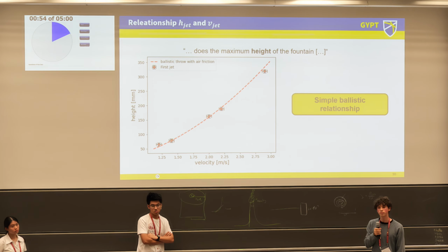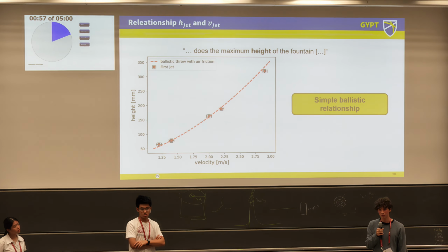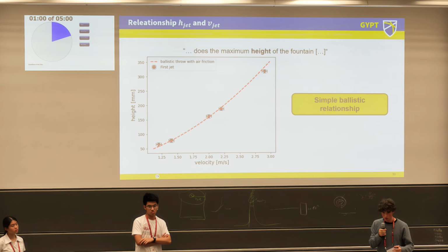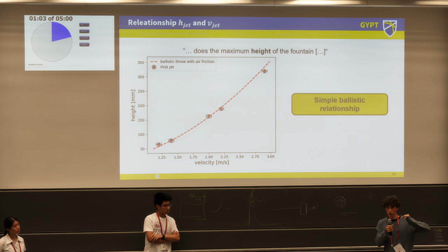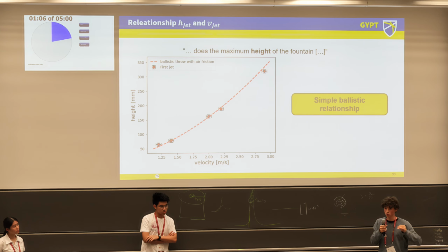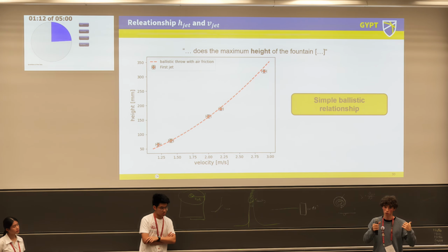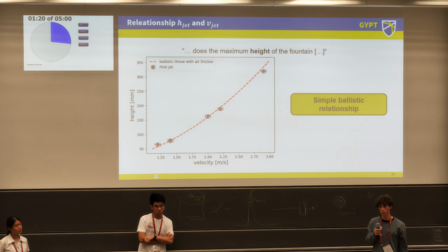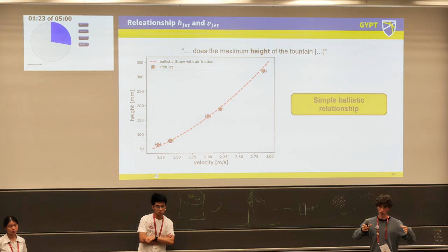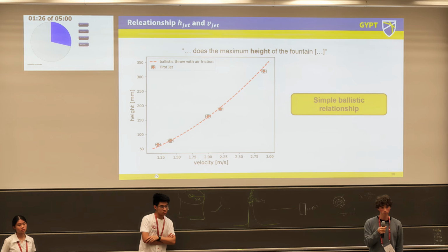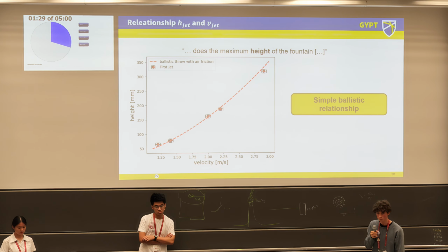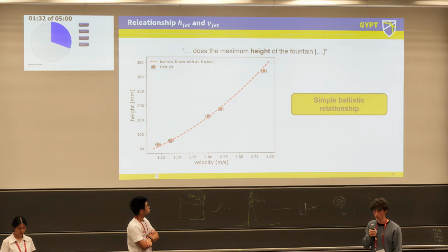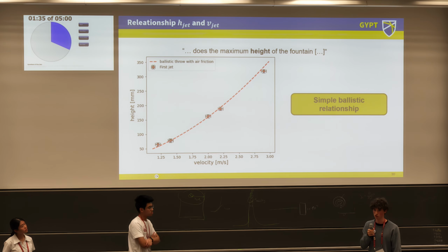I would give you the task to form a 1 meter high jet. How would the wing have to look? So we were able to see that as we increase the impact velocity of the wing, it was directly proportional to the jet velocity. So that would be one point, and also decreasing the inner radius and increasing the outer radius also maximizes it. Because with a smaller inner radius, there's a geometric effect of forcing the kinetic energy transfer from wing to the water through a smaller hole. So higher drop height than the large radius with a very small hole in it. One last question. Are all your error bars theoretical error bars, or is it just standard deviation? It's a standard deviation of experiments.